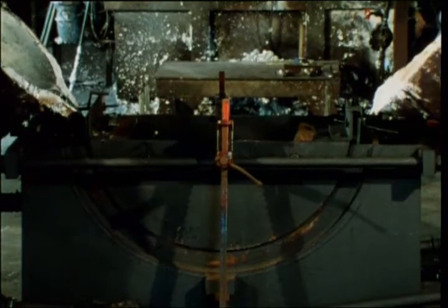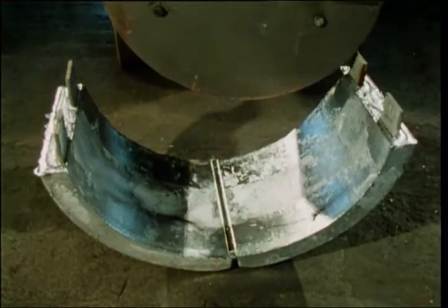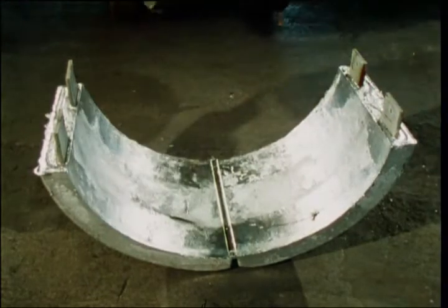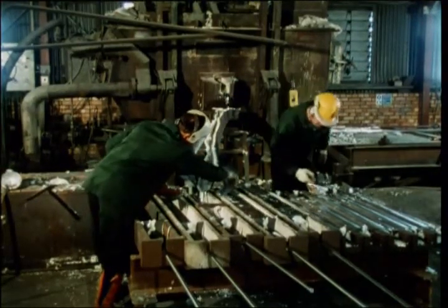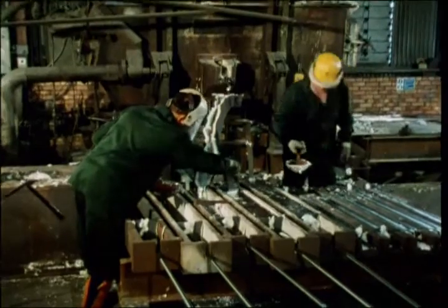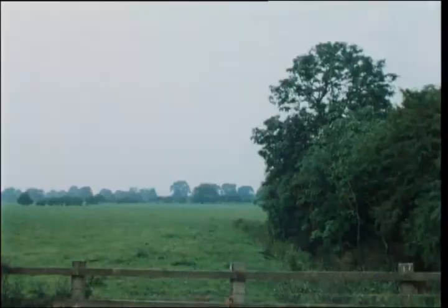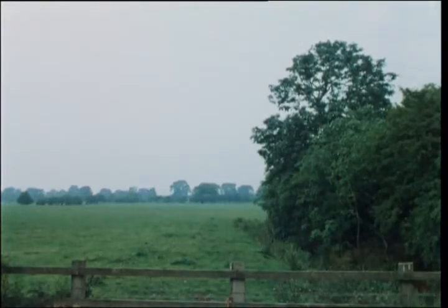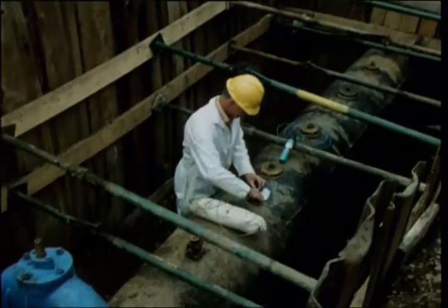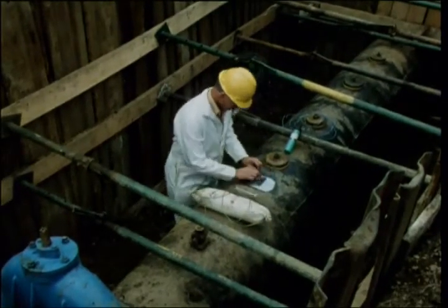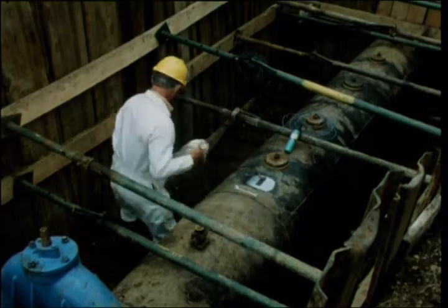Joints in pipelines lying on the seabed are protected by zinc bracelets. For the best results, anodes of zinc or magnesium are cast in a range of shapes and sizes. To ensure protection in the ground, the anode is connected in good electrical contact with the pipeline, and they will, of course, both be buried.